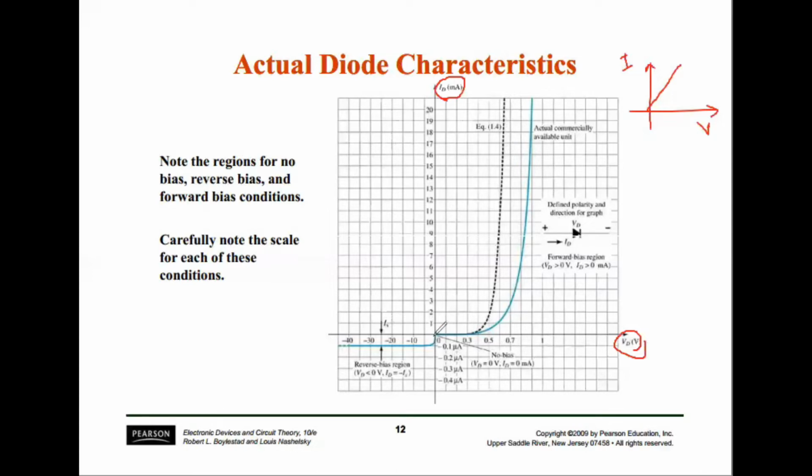When you are increasing the amount of voltage up to a certain point, there will be no current or a very negligible amount of current. After some threshold value, here 0.3, the current will increase in an exponential manner, but not in a linear manner. Similarly, here you can see that the current is also not increasing in a linear manner.